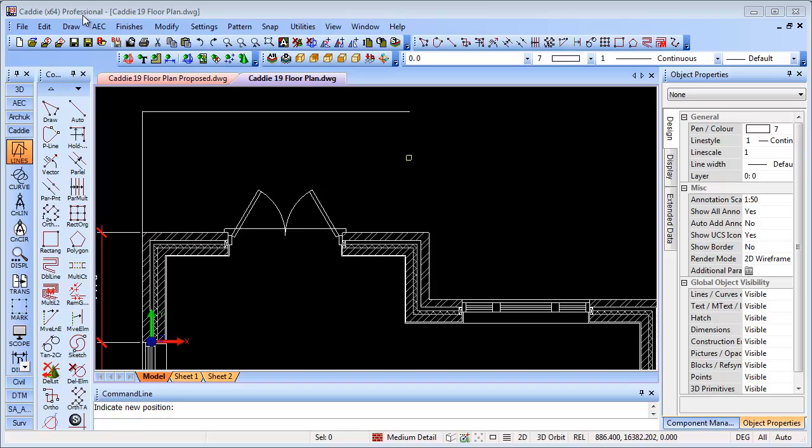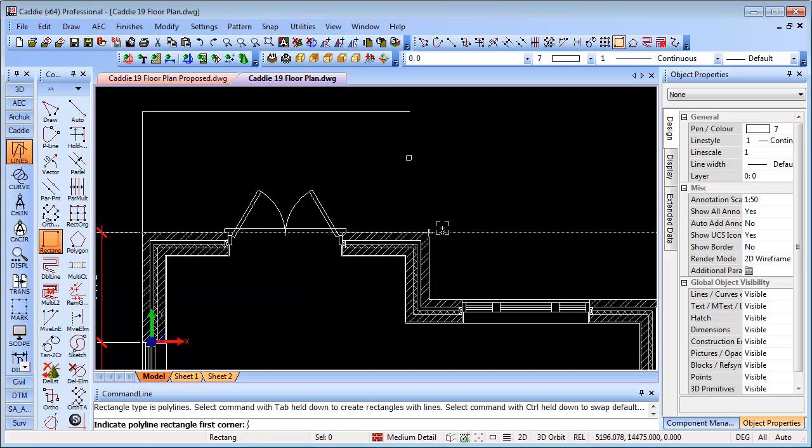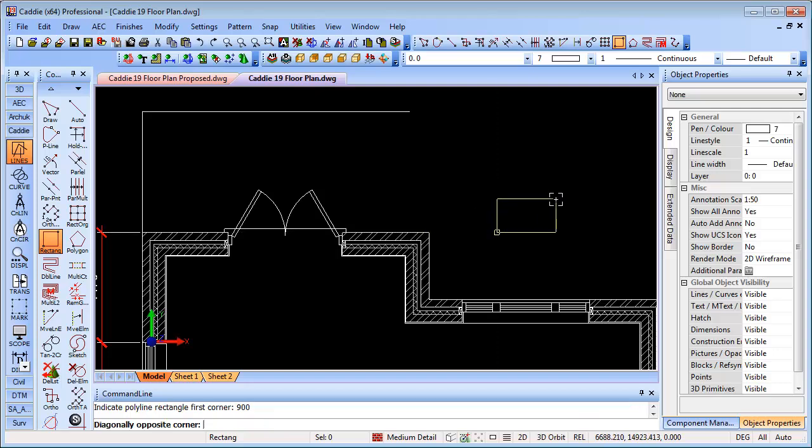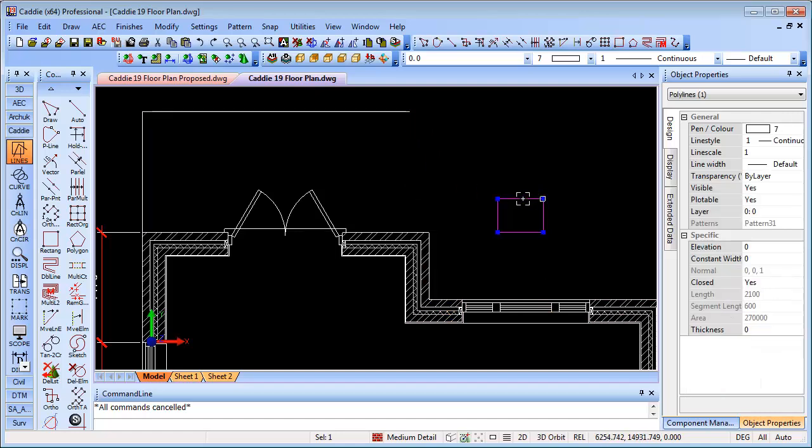Worth remembering and noting that this functionality can be used both in drawing and editing too, moving things around, in fact any part of using Caddie. So if, for instance, we were drawing in a rectangle here, we could use the equals, select our point there, just hover over it, press the equals button. In the direction now, type in, say, 900mm. That will take us 900mm in that direction. We could type in 600, 450 to give us our inspection chamber. But if we wanted to move that and line it up with the end of the line that we have there, simply select it, choose our move, pick the locating point, and then tie it in with our point there. So very free, very easy, very useful for drawing, modelling and editing within Caddie.